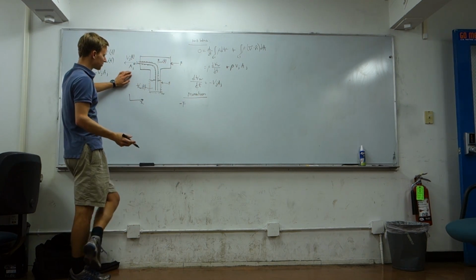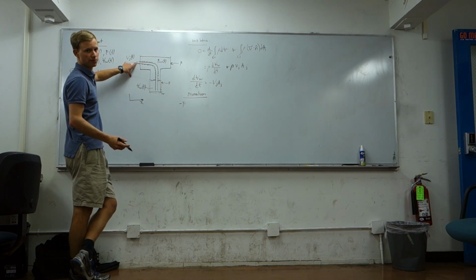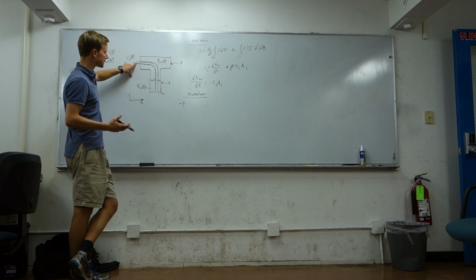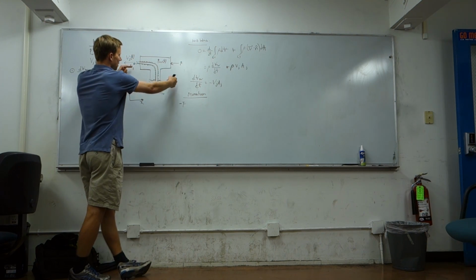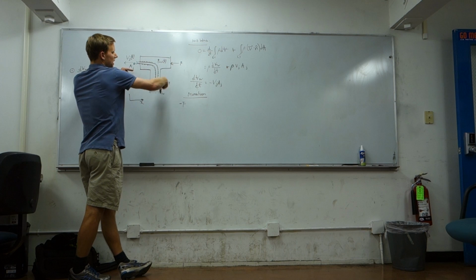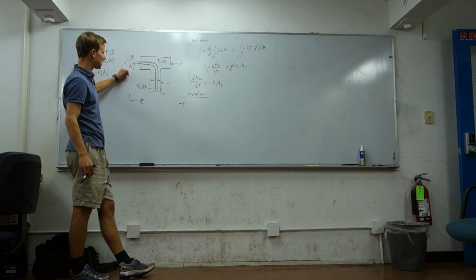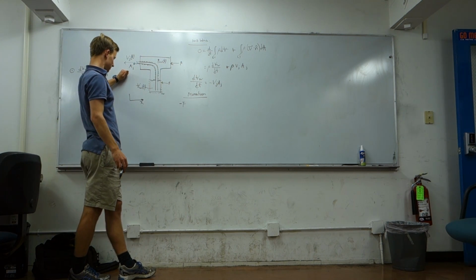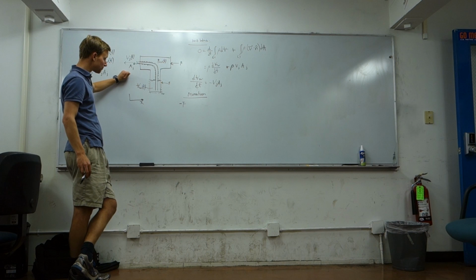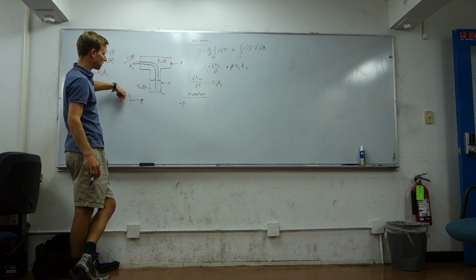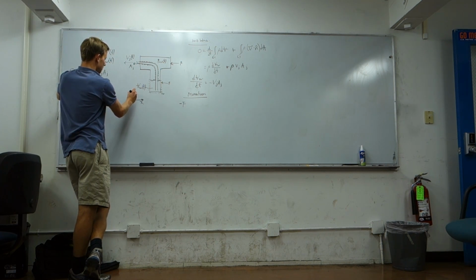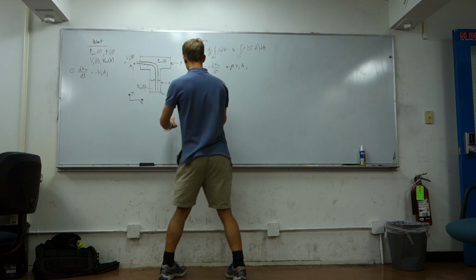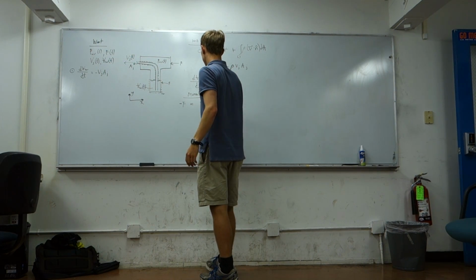We could do a pressure force over here, but it's just a free jet expanding out to atmospheric pressure. So it's counteracted by all the atmospheric pressure on the opposite side of the control volume, so there's no pressure forces. And the only body force we deal with typically is gravity, and the gravity is acting in the y direction, so we are okay with just negative F. And then our accumulation term,